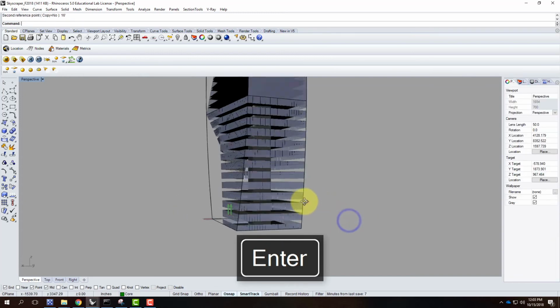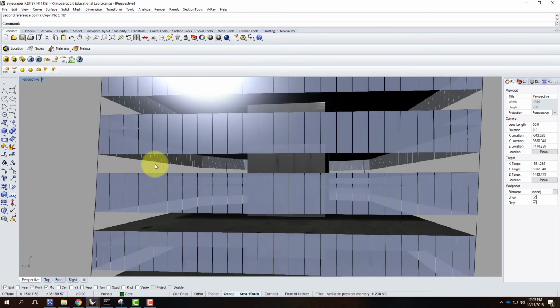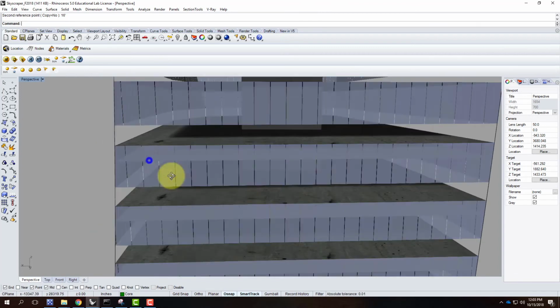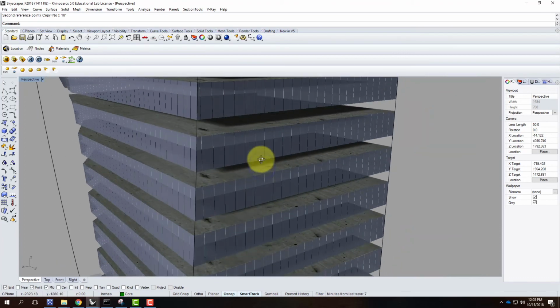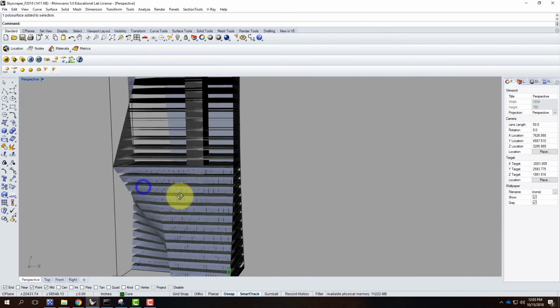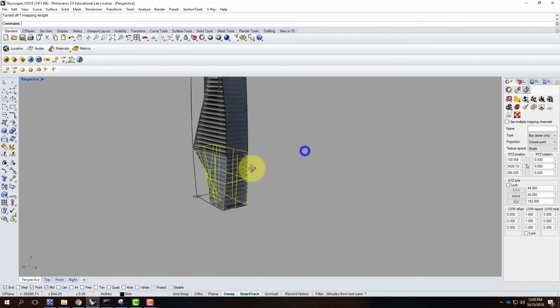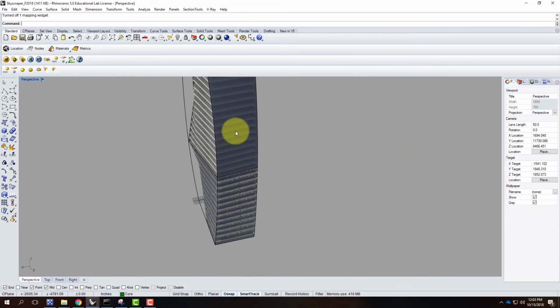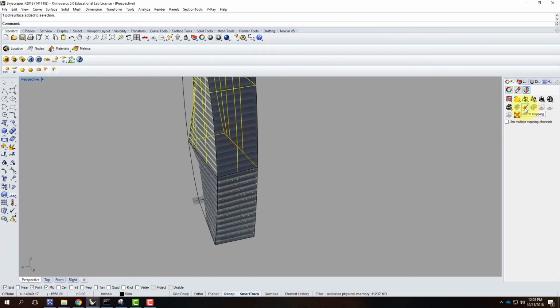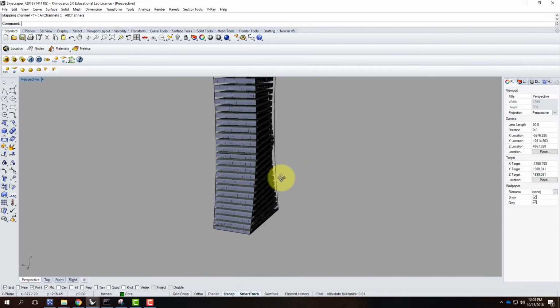And you can see that as I do that, it starts to divide this up into little individual panes of glass, which will help the overall look. I know the bottoms of these are transparent. They're not supposed to be, but it's the way it previews. Sorry. So we can also see in now, and we can see that my floor texture mapping is not the best. So I'm going to need to spend a little bit of time texture mapping that. I can hide the mapping widget now. And I can also copy my texture map onto this surface up here. So I'll take the surface, I'll say match mapping to that surface there, and now it matches all the way up.